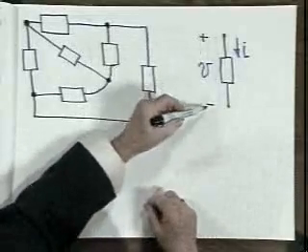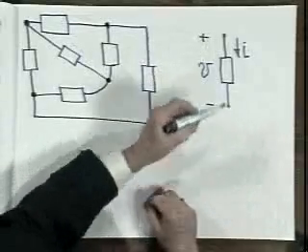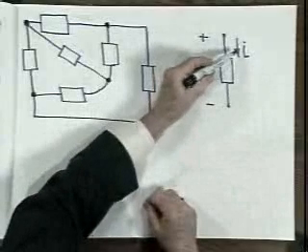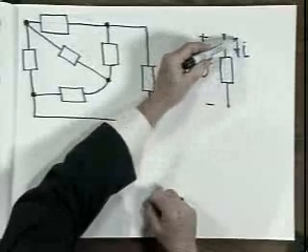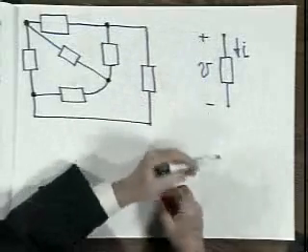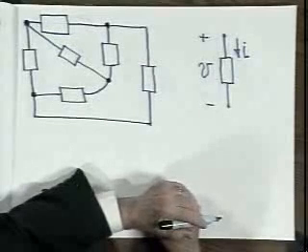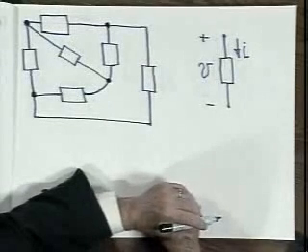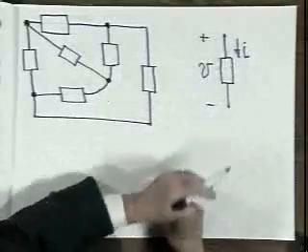But once you have made that choice and specified plus and minus as defining the voltage V, then it is important always to associate the current that goes with that element as being in at the terminal where the positive sign appears. That convention, and it is simply a convention, will be used throughout this instruction, and it is convenient and essential to use because once you settle on that convention, there is no longer any doubt about the form of the current voltage relationship for the element.